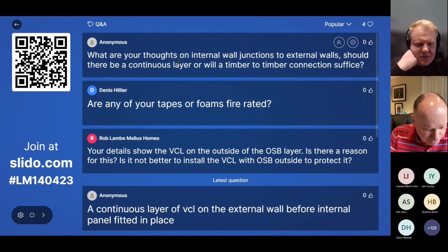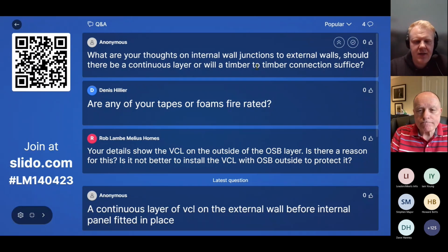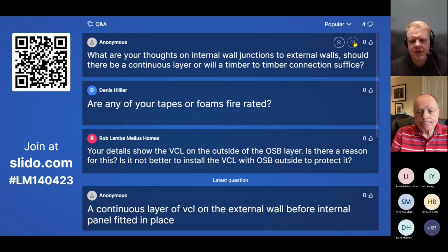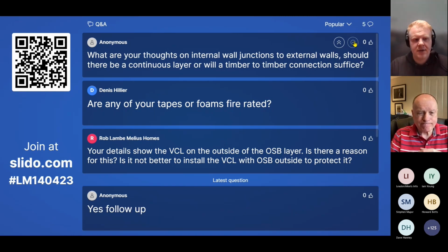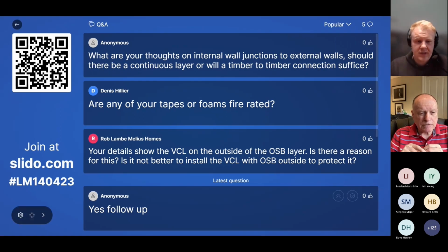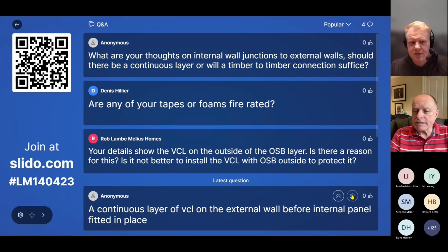Generally, you are always aiming to have a continuous, leakage-free vapor control layer. In every way, any discontinuity of that layer may cause a problem in the end. So yes, there should be one, or on the outside it makes sense to use one.